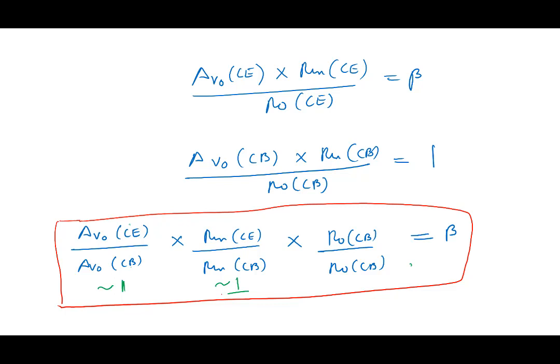Either it will be superior in terms of output resistance, or it will be superior in terms of input resistance, or it will be superior in terms of gain. You can see a comparison between them. Common emitter versus common base, right? You can see clearly that in terms of gain, input and output resistance, this amplifier common emitter is superior.